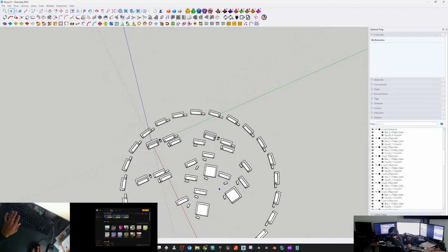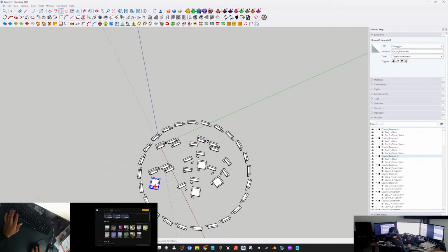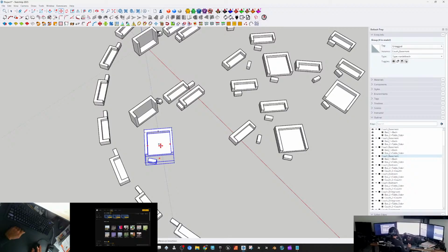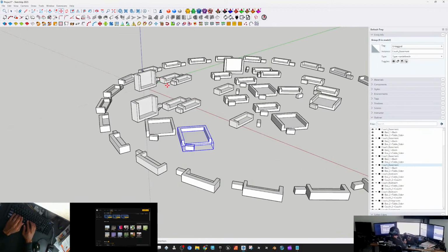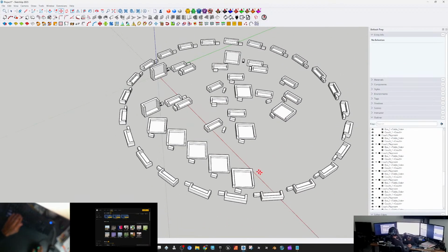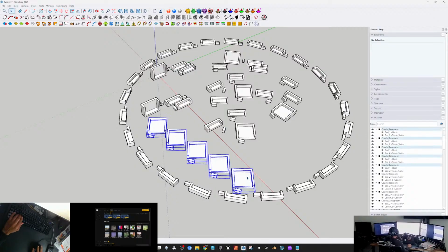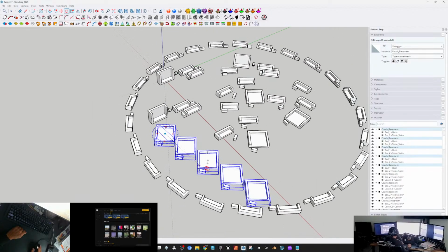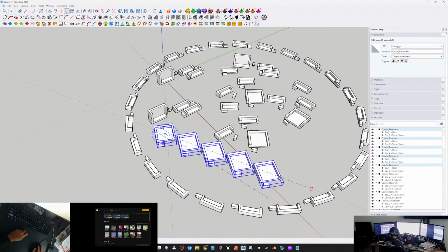You can also take this bed group and let's move it, and Control click, and let's put it here. And then let's Control click and move it again like this. And this is like a nightclub type of setup. So we're gonna click and place it there. And then I'm gonna do X4, enter. And that duplicates it 4 times. I can now grab all 5 of these, press Q, we're going to just click on a random part of this one couch here. Then I can use a point on one of these other couches as my pivot for how I want to rotate this.